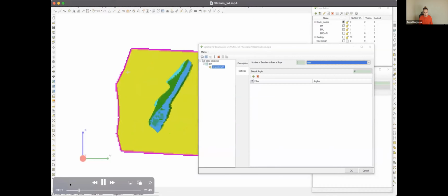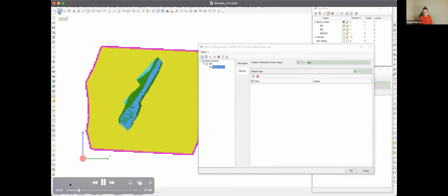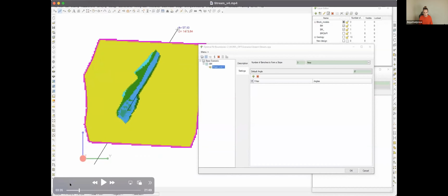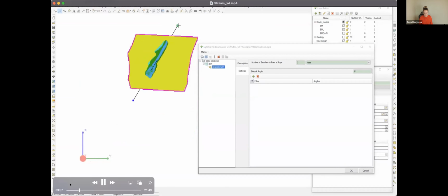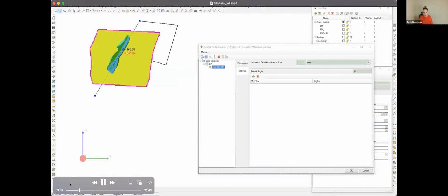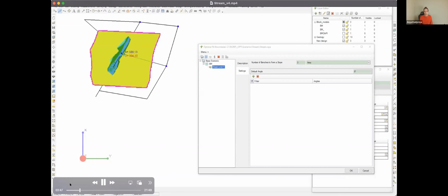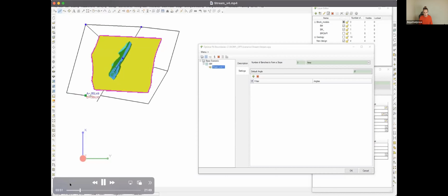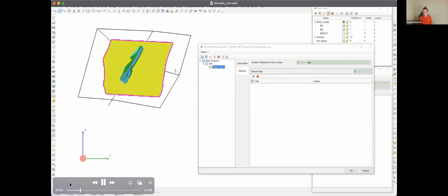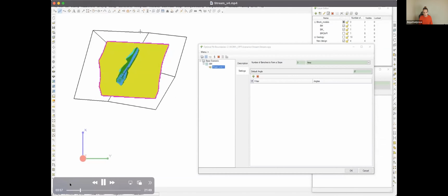So in our example, let's set the angles of slope by area. And in order to do that, you need to create them first. Under existing conditions, these geotechnical areas must be identified by geotechnical experts. So in this example, we will use construction of polylines, and we are expanding them so we can get the required result. So let's create 4 geotechnical areas.